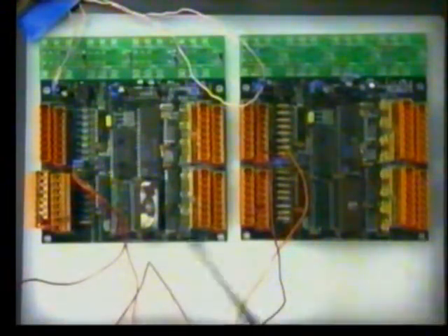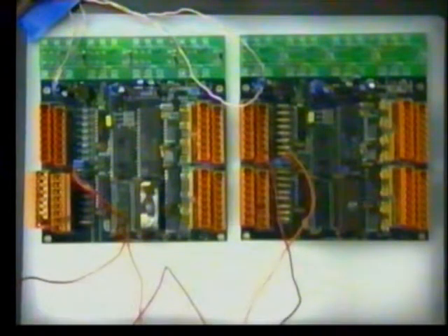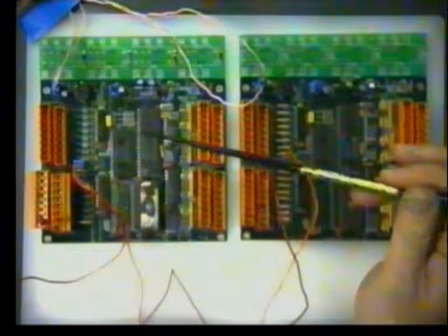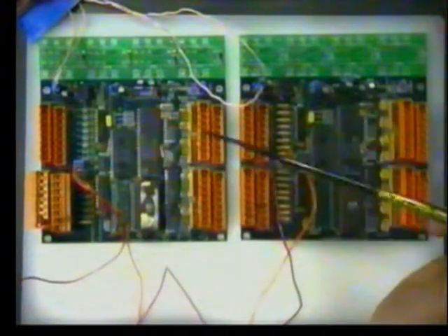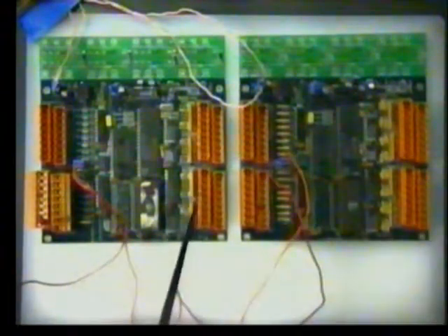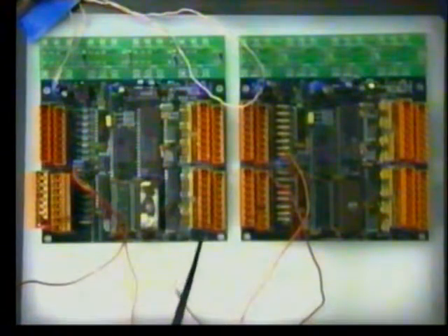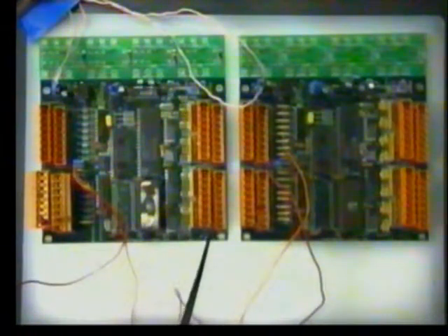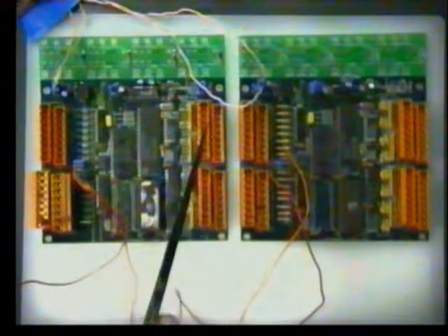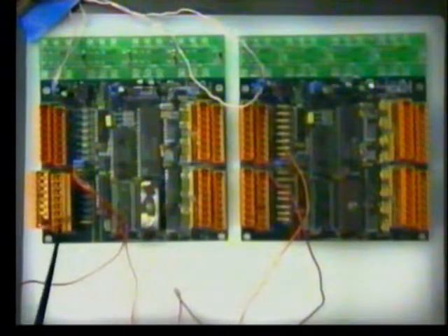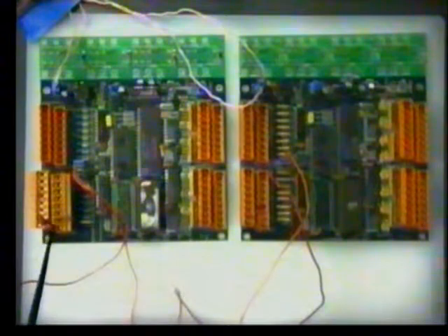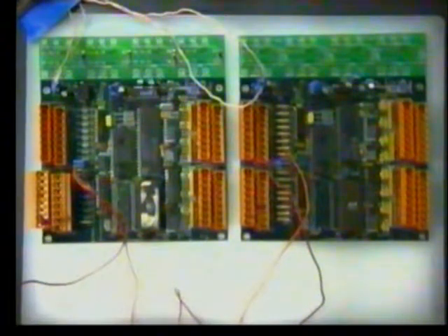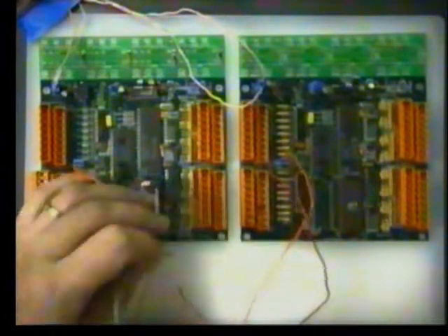Here we have two CAN bus cards. These are general purpose cards used in factories. Here we have a processor and we have some input devices. On this side here, these are switched inputs. When we connect switches across these two poles, we can detect a switch closure or switch opening. And here, just for some simulation, these are actually high current outputs, but I've put a light emitting diode onto them so that we can actually see the switches closing.